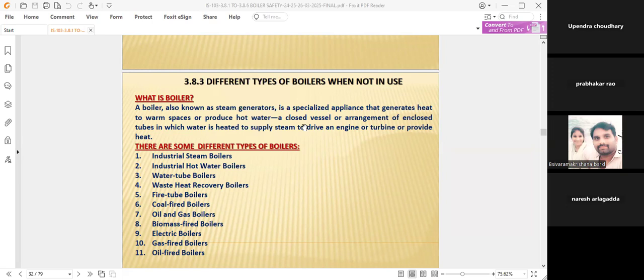That means in the boiler, you are combusting the fuel like coal or liquefied fuel or electrified boiler and all. It will give HP steam by boiling the feed water. Therefore, that HP steam is sent to the turbine. The turbine rotor will run. Therefore, the turbine will give power as per the design of megawatts, and along with the power, it will give MP steam, that is medium pressure steam, as well as low pressure steam, LP steam, for the usage of process cleanings, process heatings of various chemical industries or other industries other than chemicals.